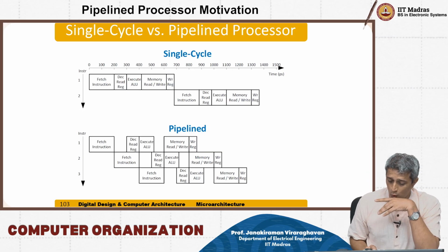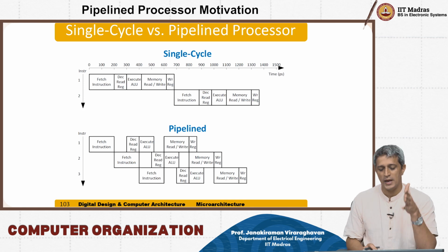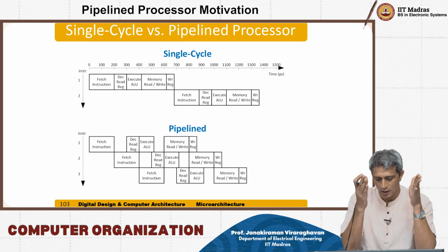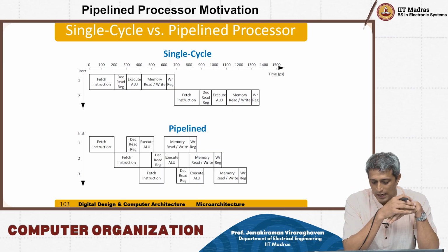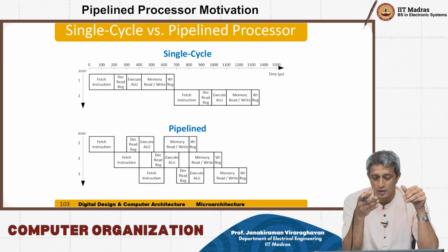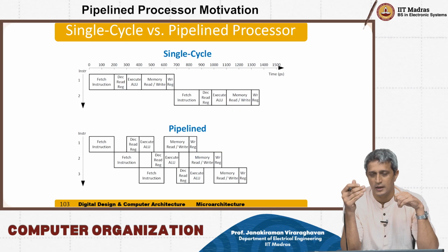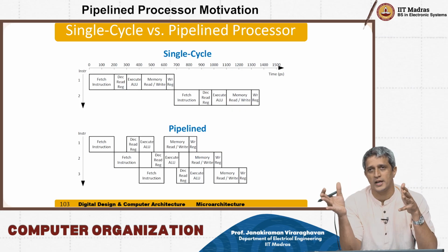So what we are now doing is saying, look, I will make the clock period some particular amount of time, and I am going to fetch, decode, execute, do memory access and register write back in different clock cycles.